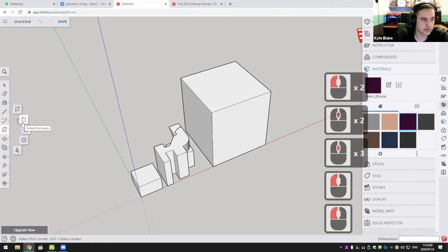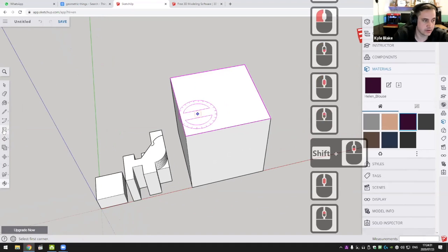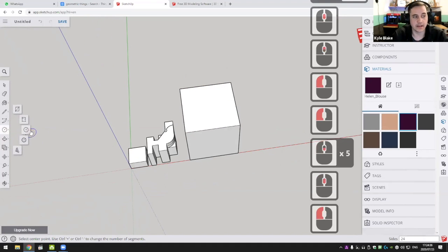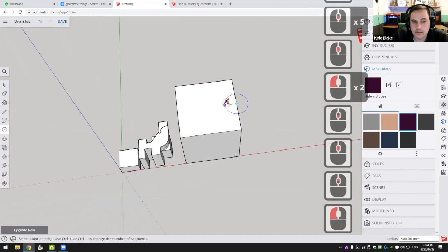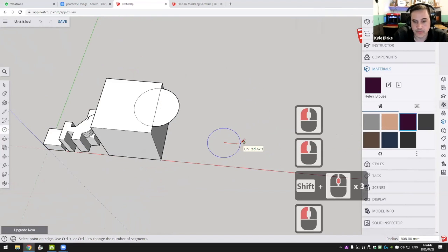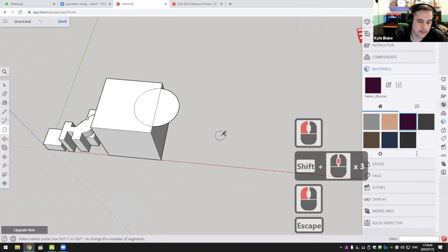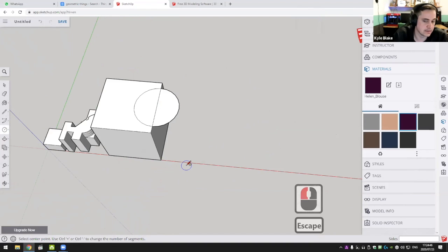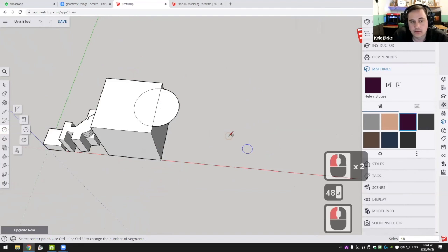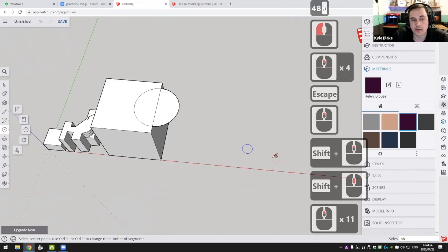We've got rotated. Okay, don't worry about the rotated rectangle for now. It is quite complicated to use. Underneath that, we've got a circle, which allows you to draw any size circle. You can also specify the sides of it. So on the bottom right-hand side of the screen, it says sides 24. You can up that to 48 if you wanted a much smoother looking circle.